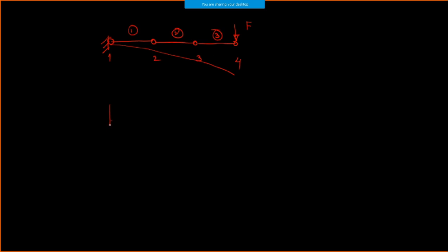I'm going to determine two things here. One is vertical displacement. Here it is zero. I will have some displacement U1 here, U2 displacement here, and U3 displacement here. When I match this U1, U2 and U3 at common nodes, nodes 2 and 3 being common, it satisfies C0 type of continuity, also called convergence.